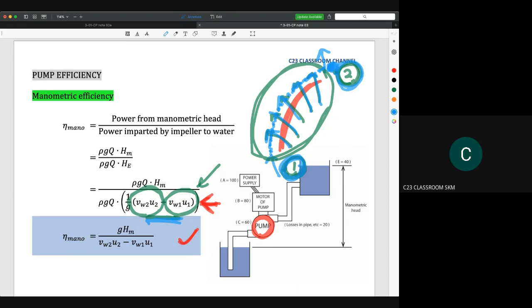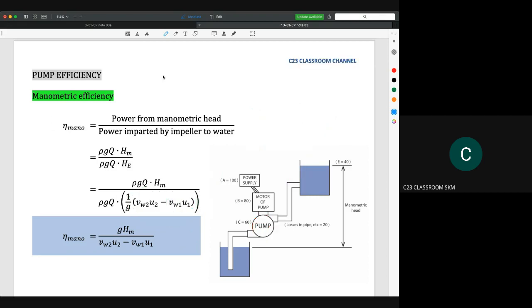Okay, you must go back to the idea of a pump. A pump is a device that gives energy to the water. That's why after water flows through the blade, it will receive a lot of energy. So in a simple sentence, you should understand that Euler head is the energy being transferred inside a pump, and the manometric head is the actual height of water being transferred.